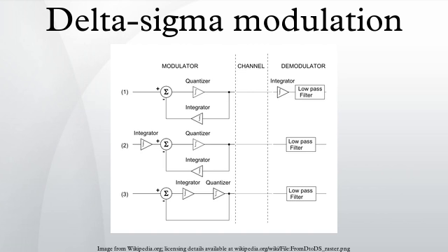In delta-sigma modulation, the accuracy of the modulation is improved by passing the digital output through a 1-bit DAC and adding the resulting analog signal to the input signal, thereby reducing the error introduced by the delta modulation. This technique has found increasing use in modern electronic components such as converters, frequency synthesizers, switched-mode power supplies and motor controllers, primarily because of its cost efficiency and reduced circuit complexity.